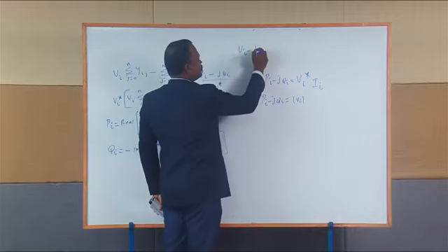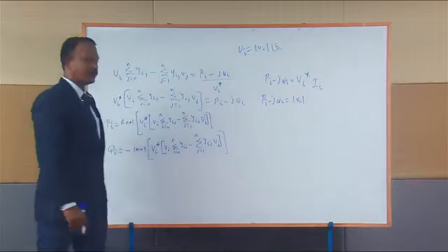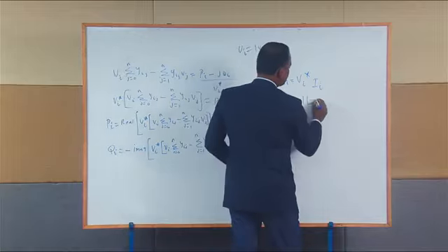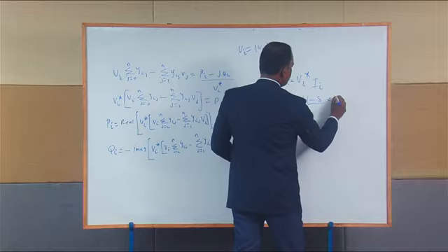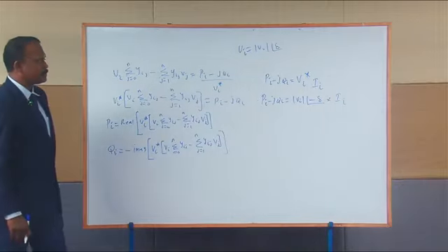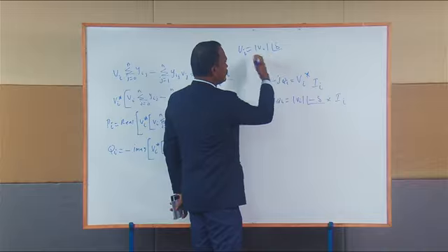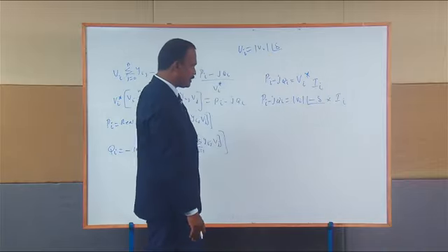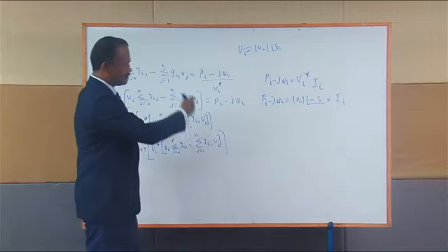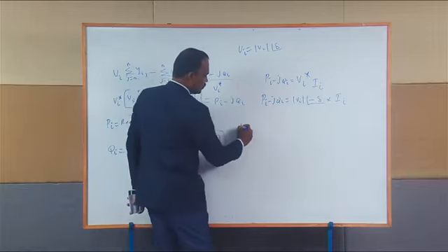Vi is equal to modulus Vi angle del. This del I call the voltage angle. Then I can write this is equal to modulus Vi angle minus del into Ii. Is that clear? Because Vi is equal to modulus V angle del, I just take the conjugate and put a minus sign for this angle.